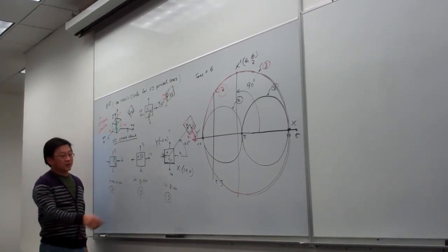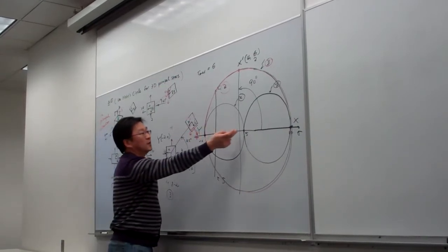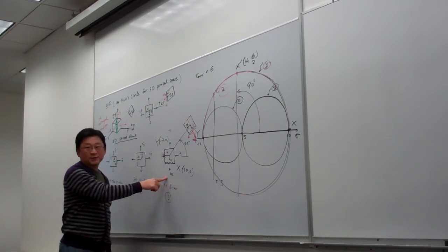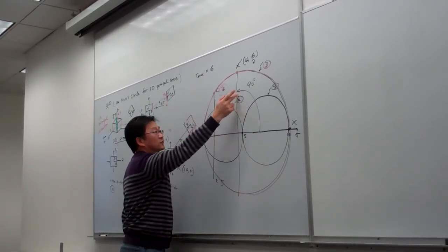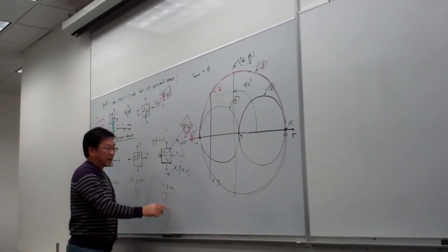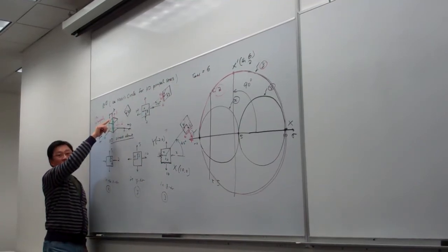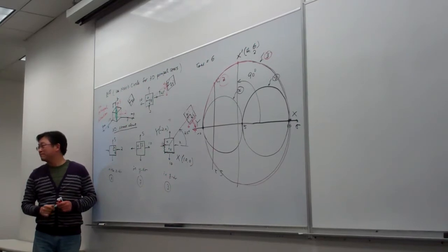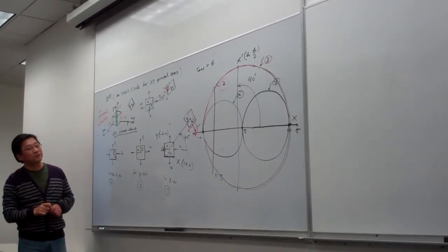And that can be told from this, because the 45 degrees we identify corresponds to the biggest circle. The biggest circle is about this viewpoint. And how much? Rotating on the Mohr circle by 90 degrees means rotating about the z-axis by 45 degrees. So that means we're back to here, we work on the original, then that should be in this plane. Is that okay? Okay, that should be a little bit more straightforward.